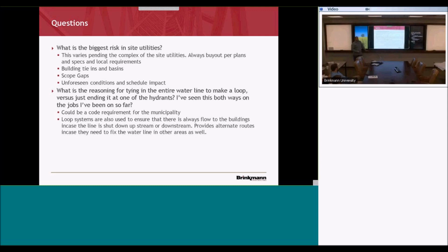The subcontractors call for their own utility locates. I like to do one myself when I get a project. If we're getting ready to go have the site, if I've got time, I'm going to call one in just so I have one up front. So I know when I'm walking the site, hey, there are some utilities here, to help familiarize myself. But each contractor that's going to be sticking a shovel in the ground is required to do their own utility location and make those phone calls.